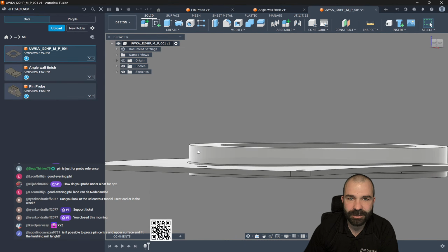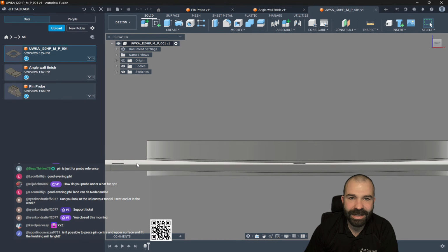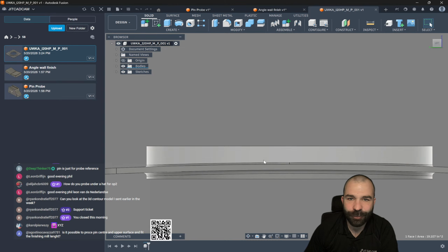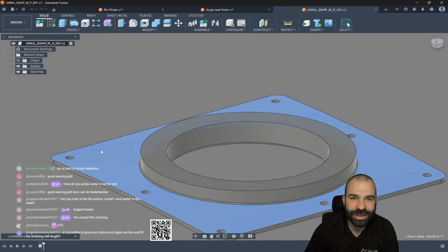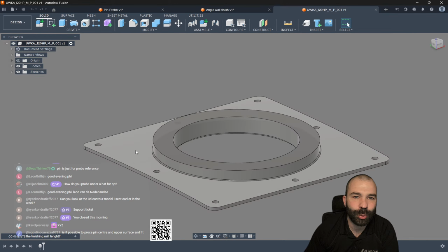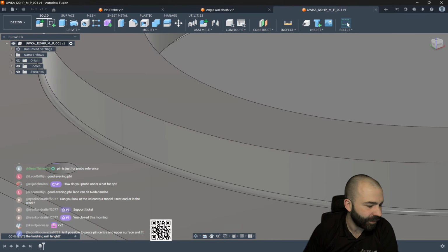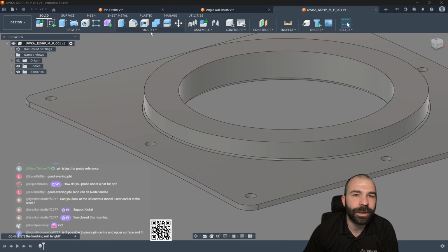So, let's see here. Is there some undercutting? What do we got going on here? We got a nice little concave kind of profile. We got a little warpage going on here. So the question now is how could you run around the outside of this bore? And I would assume what he's really looking for is to get this chamfer or this fillet down at the bottom more than anything. So with that, there's a couple of toolpaths that would work out good for this.